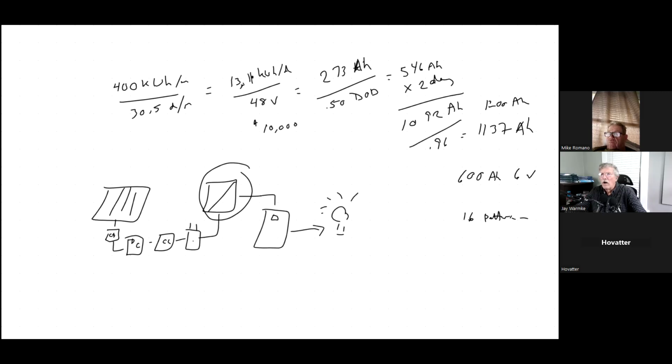Rather than going through all the other ones, I think what I'll do is the other math that you're going to want to practice is string sizing. So string sizing, what's the minimum? What's the maximum in a string? That's one that you're going to need to know. Voltage drop, as I said, array sizing, battery bank sizing. I think those are kind of it for the math questions.